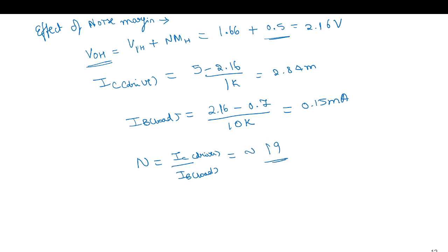So you can see with this noise margin term addition, my number of gates I can connect has reduced. So noise margin reduces the fan-out.